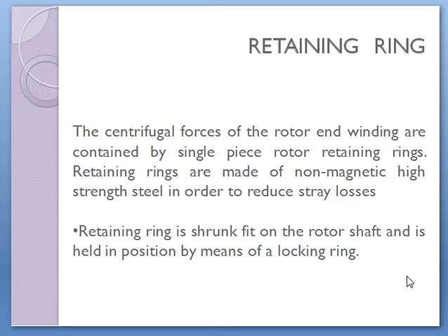The centrifugal forces which may be developed during rotation are limited and minimized by a single piece retaining ring, made of non-magnetic high strength steel in order to reduce the stray losses.